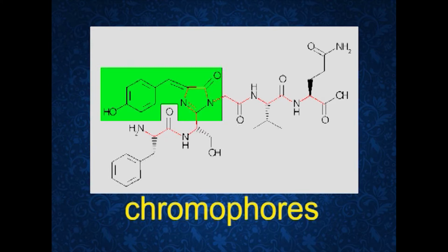Organic pigments are usually brighter, stronger, more stable, have better gloss development, and some absorb UV light, preventing it from damaging the binder. Now comes the inorganic pigments. Inorganic pigments are heat and light stable, much cheaper than organic pigments. They are used for specialist pigments, that is anti-corrosion. These are the pigments having improved elasticity and durability. Now comes the solvent. Solvents are required for the purpose of even mixing of paint components. This also makes them easy for application.